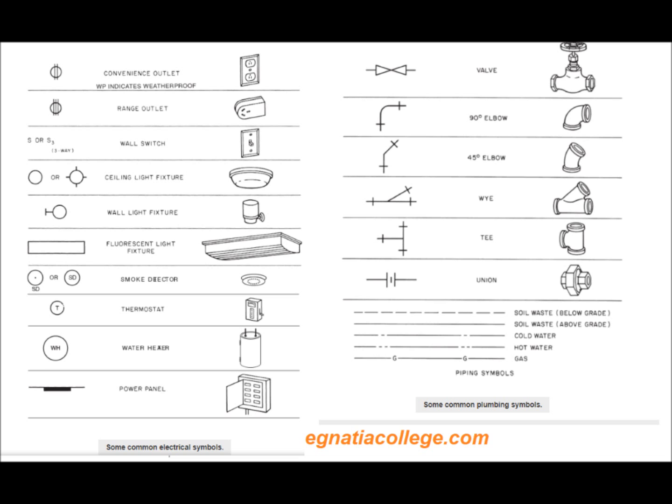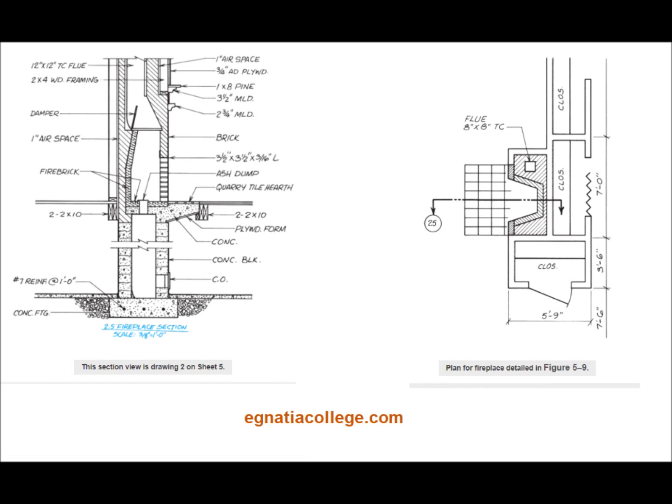Reference marks. A set of drawings for a complex building may include several sheets of section and detail drawings. These sections and details do not have much meaning without some way of knowing what part of the building they are meant to show. Callouts, called reference marks, on plans and elevations indicate where details or sections of important features have been drawn. To be able to use these reference marks for coordinating drawings, you must first understand the numbering system used on the drawings.